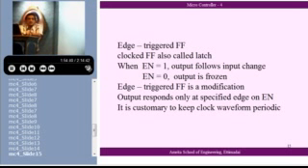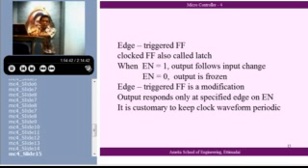Second thing is, whenever you are putting in an edge-triggered flip-flop, that En signal will be called a clock signal. That is at regular intervals, I just see what the S and R are and I do an operation. It is a clock signal. The clock signal is kept as a periodic signal. I am just slowly building up what is required for a processor. So I have an enable signal, I make it an edge-triggered operation, I make that enable signal a periodic waveform. It is a regularly operated clock.